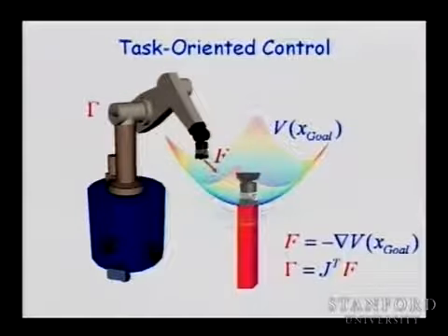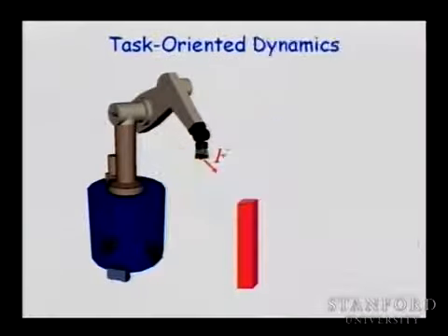As I said, the relationship between forces and torques is also the Jacobian. So the Jacobian plays a very important role. And then to compute the dynamics, all we need to do is to understand the relationship between forces applied at the end effector and the resulting acceleration. Now, when we talked earlier about Newton's law, we said mass times acceleration equals force. And the mass was a scalar. But this is a multi-body system. And the mass is going to be a big M mass matrix.